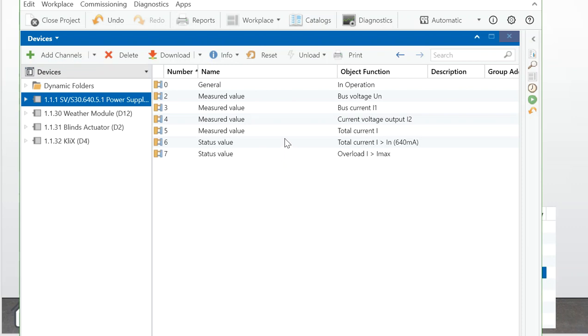And we can use it and make the alarm. But remember that in KNX, if you want to use the key information, okay, you should report or transmit this data to another line. Okay, for example, you have the monitoring in the main line, your power supply unit is in a secondary line with diagnostics. The information from the diagnostics should always go to the main line to make the decision, okay? Because if it's in its own line, so if something happens, what do you want to do?